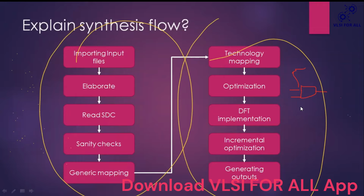So the tool will remove those buffers and connect one cell output to another cell input directly instead of going through the buffers. Logic restructuring includes all this, and it will try to reduce the number of logic levels between the start point and the end point. It will also try to remove combinational loops. The tool will try to avoid all these things.